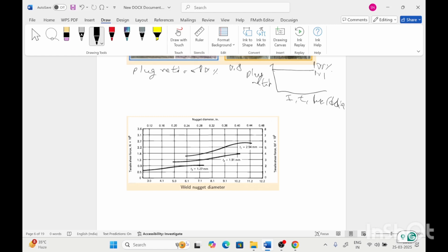So the main point of this tensile testing of the plug weld joint is to identify strength. We generally identify the strength required to break anywhere in the component, plus the plug size.